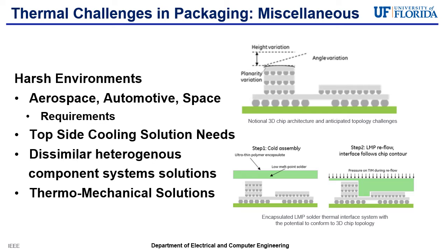The diagrams on the right illustrate the concepts of a notional 3D chip architecture with anticipated topology challenges, highlighting the need for TIM, also known as thermal interface materials, that can conform to the 3D contours of advanced chip designs. The depicted encapsulated low melt point solder thermal interface system suggests that a method to create a more effective thermal pathway is on the way for complex chip architectures.